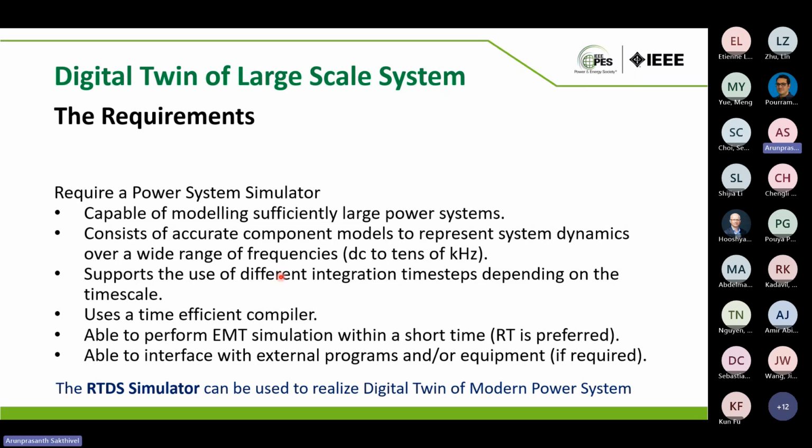And also it should support the use of different integration time steps so that we can accurately represent the time scale that we want to see. And then it should have a time efficient compiler. This is a very important aspect of the simulator, because if a system takes several minutes to compile, then it's going to add up to the simulation time as well. And it should be able to perform EMT simulation within a short time.